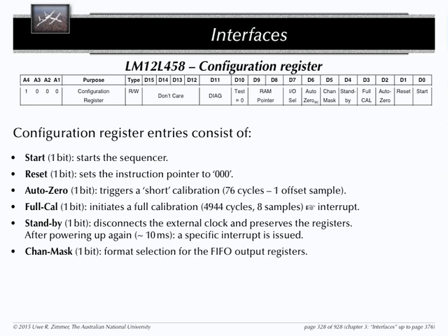Once you have this translated to data structures, you are type safe. You cannot set the wrong thing accidentally just by using some numbers wrongly. What do you have? Start the sequencer, reset the whole thing, auto-zeroing everything. That's the short calibration. You have a full calibration, which takes almost 5,000 clock cycles of that thing. And this takes so long that it automatically produces an interrupt by the end of this auto-calibration phase. You can set it into standby, powering it down. What else do we have?